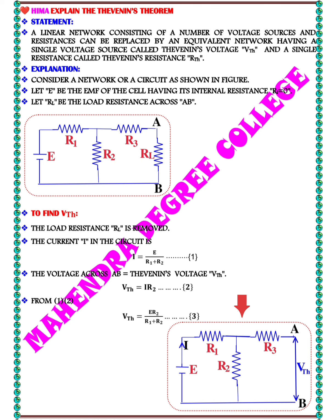A circuit with voltage source E, resistors R1, R2, R3 and a load resistance RL is considered. To find the Thevenin's voltage, we remove the load resistor. In this case, the load is considered to be between points A and B.